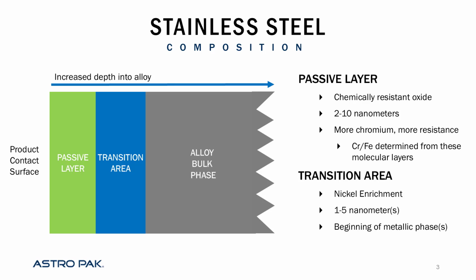Chromium exists all throughout the stainless steel in this nice little sketch of a cross-section of stainless, but it primarily migrates to the immediate surface of the alloy. And here it reacts with oxygen and forms a chromium oxide surface, or chromium oxide layer. This is the passive layer.